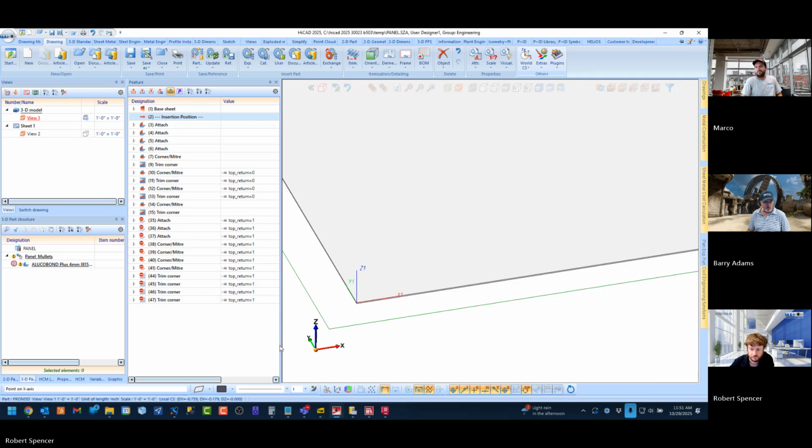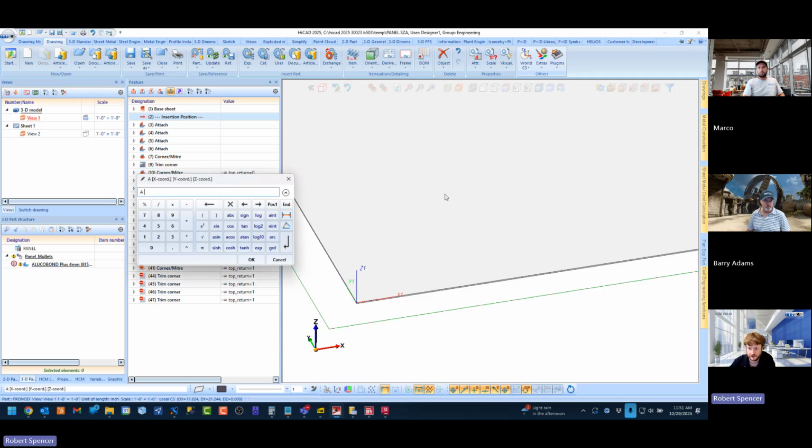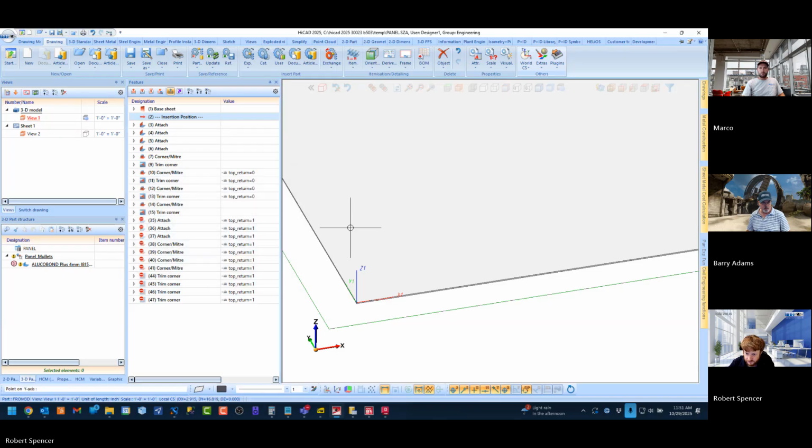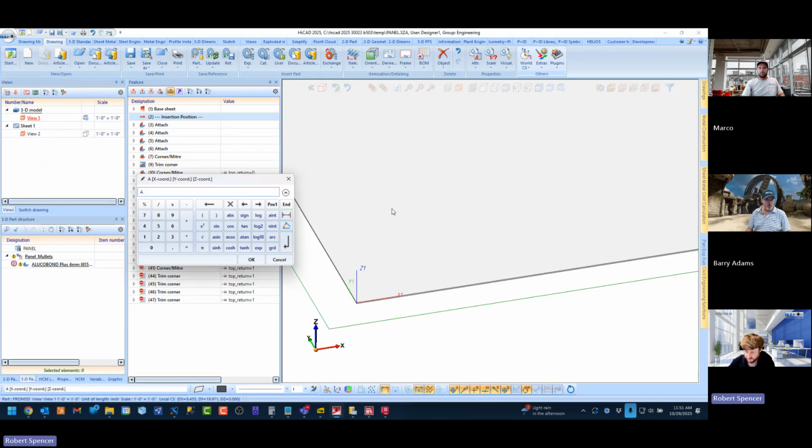Okay. Point on x-axis. Absolute again, A on the keyboard. Let's make this simple, an x directional vector. Okay, third point. Any guesses? It's going to be at the end of y. I don't think it can be a 0. Correct. I'm keeping it simple here with 1 inch in each direction.